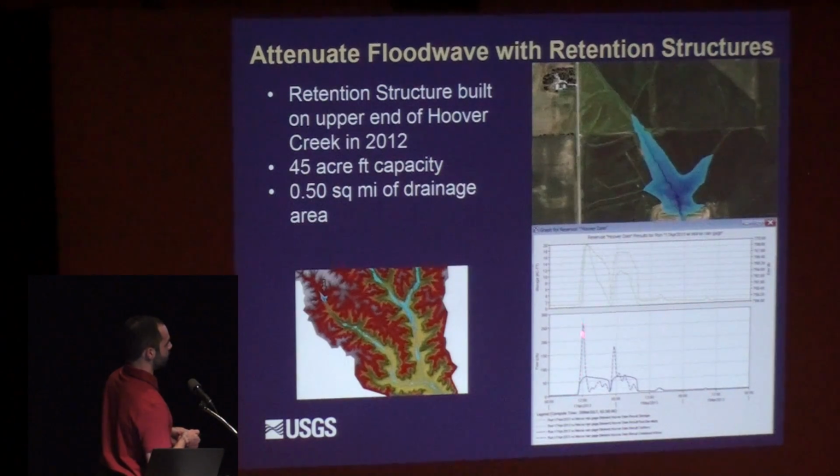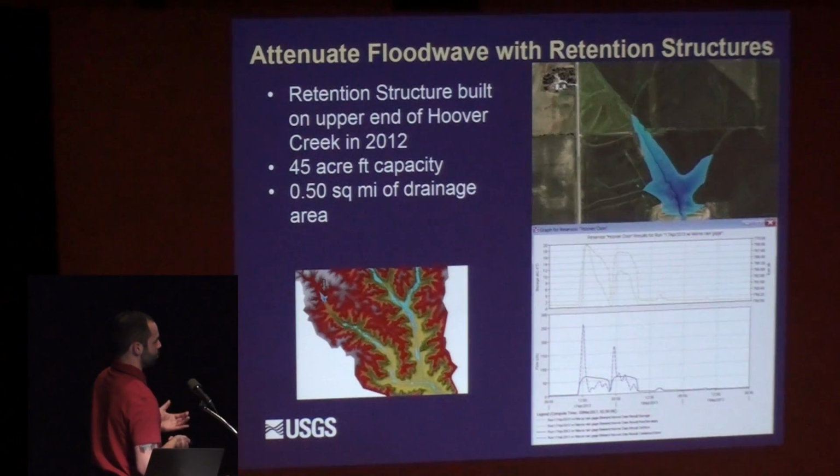This was an April 2013 event. It was receiving 250 CFS at one time at its peak, but only had an outflow of around 60 CFS, so that kind of shows how that can attenuate.